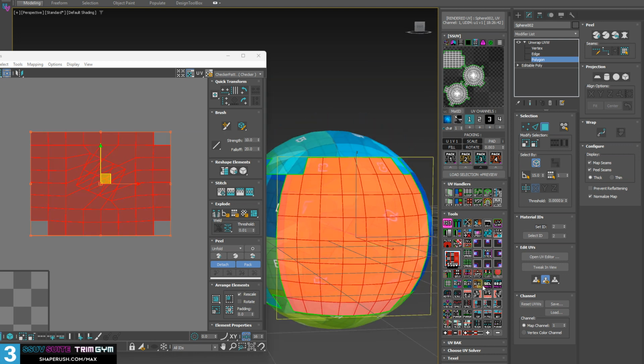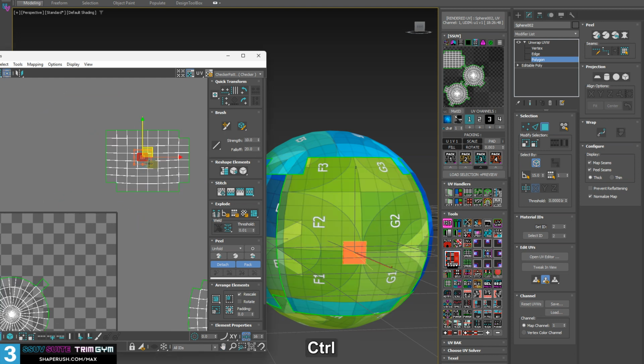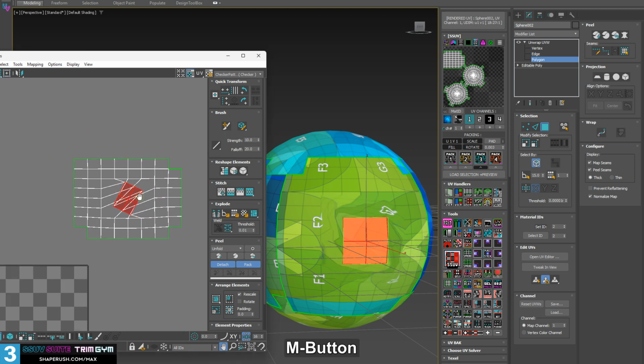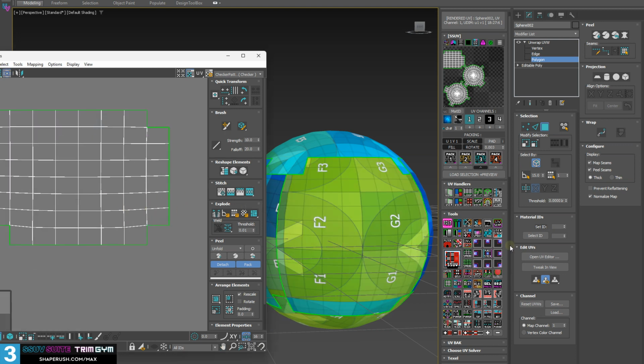So I'm going to select that, left click, and you see that the mesh has been solved for us. I'll do the same thing again. Rotate, flip, good enough. Select it all and right click, and there we go. That's been solved for us, so the edges and faces on that one as well.